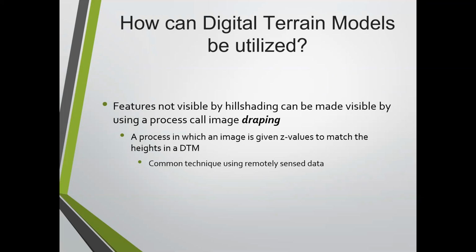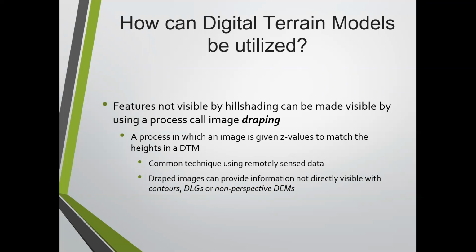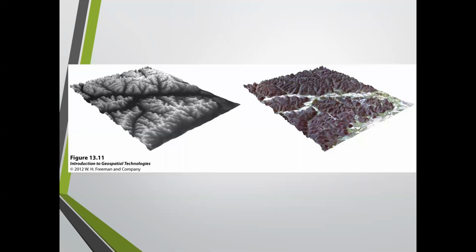And like I said, Civil 3D actually has a drape option in it. Has anybody ever used the drape option in Civil 3D by any chance? No? Yeah, check it out. It's under the DTM sections, on your surface stuff, but it's there, and it allows you to do that.